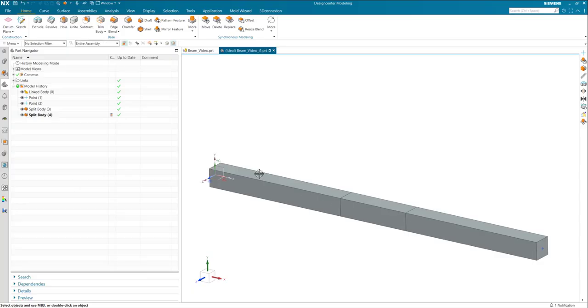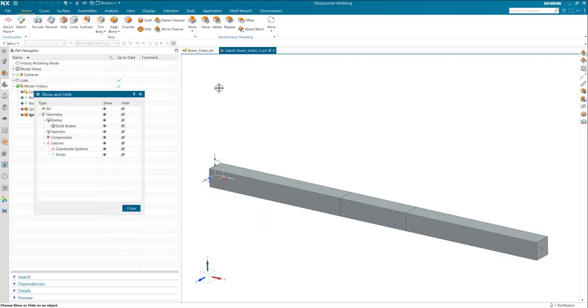All right, so when I do the mesh, it's going to create nodes or separation at these points so that I can apply a thermal load in this region. I've created points on the end so that I can establish boundary conditions there. Okay, the next thing I need to do is create these associations first. Yes, let's do that. So let's create the line.